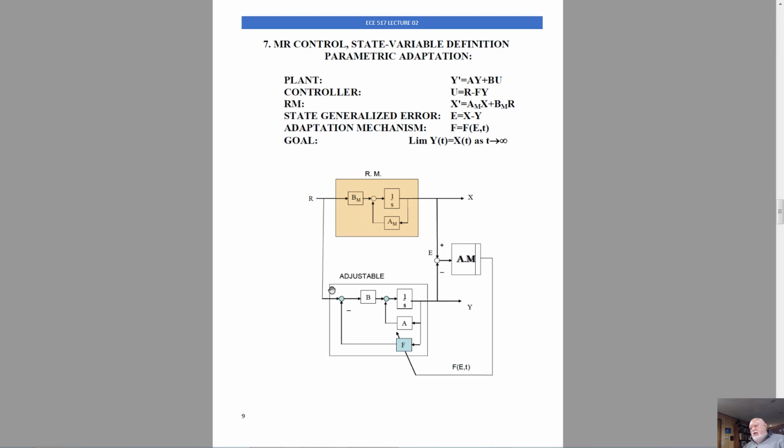All right? You may ask me, where is the filter in the reference channel? We are assuming that this filter is just a unit matrix. All right. Looking at the description of our state variable system, controlled plant, nothing new about the controller. Reference model represents the desired closed-loop dynamics. How do we know it's closed-loop dynamics? Look, input for the reference model is a reference, because the controlled plant has a different input. It's a control effort. Okay, error is calculated.